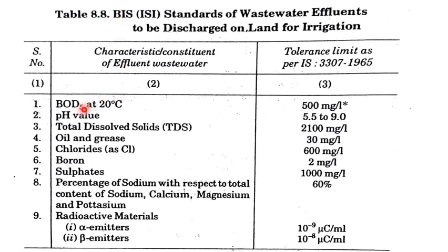Now BOD means what? Organic matter, I told you already. What is this 5? BOD5 means this test can be conducted in the laboratory. It takes 5 days to get one result, to find how much oxygen is required to decompose the organic matter.